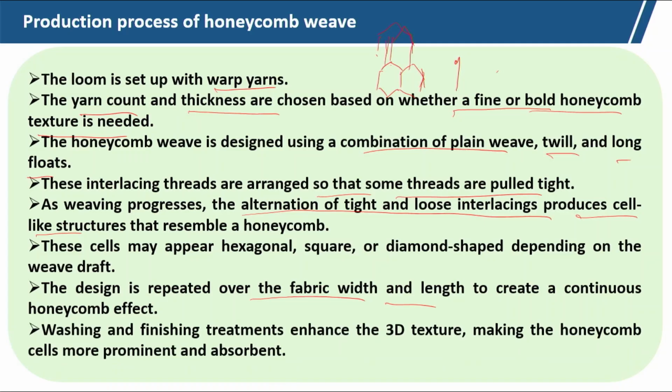Now, washing and finishing treatment to enhance the 3D texture. So, we can give different types of finishing treatment to enhance this 3D effect, making the honeycomb cell more prominent, because if the washing and finishing treatment is given, this shrinkage may take place in the yarns with the tight yarns. So, that way it will enhance the 3D effect.